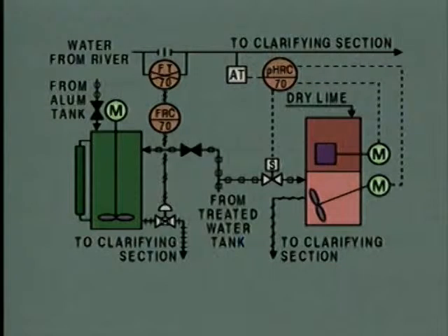The lime solution carried by the hose is made in the mix tank of the lime system, so the tank and its motor-driven mixer could be checked for visible problems. Lime is added to the mix tank by this motor-driven shaker, so the shaker could be checked to see if it's clogged or damaged. The motor could also be checked for problems. Lime for the shaker comes from a hopper that's filled manually. So another thing to check is whether the hopper contains a supply of lime.